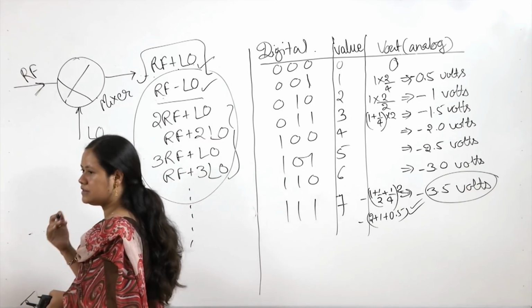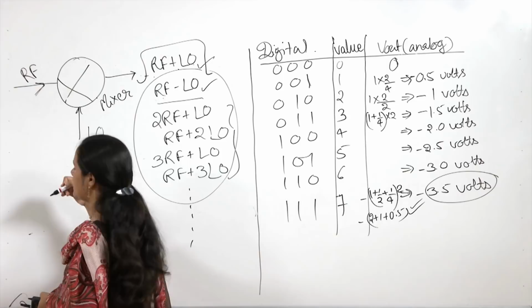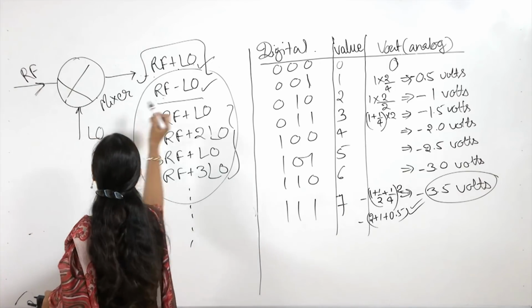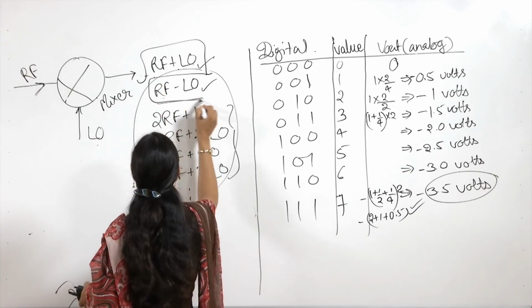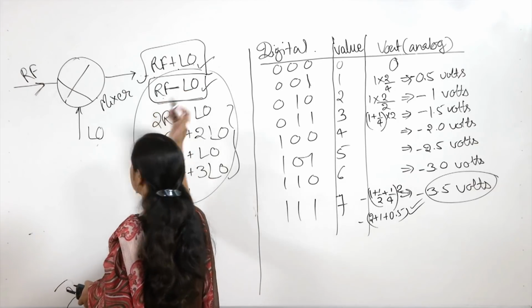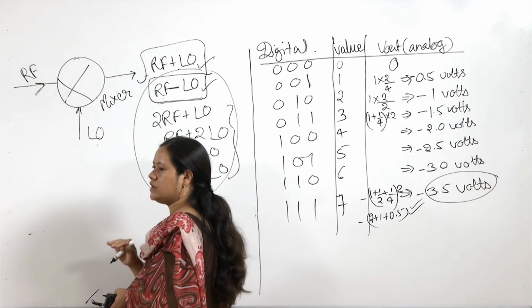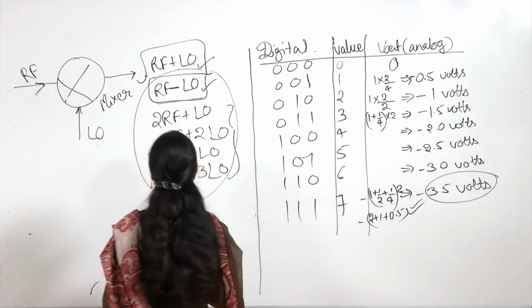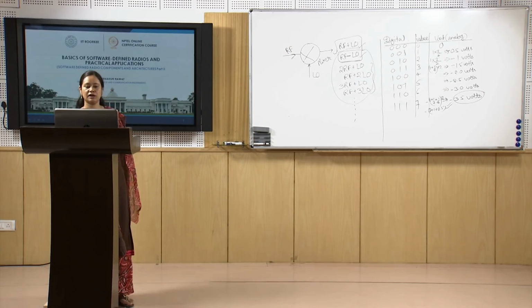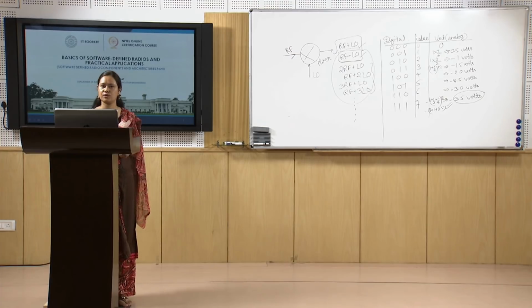Similarly, at the receiver side, when you want to down convert, we choose this frequency. So in this case, we do the down conversion, we go to the lower frequency range. So frequency up conversion is done by using nonlinear mixers.